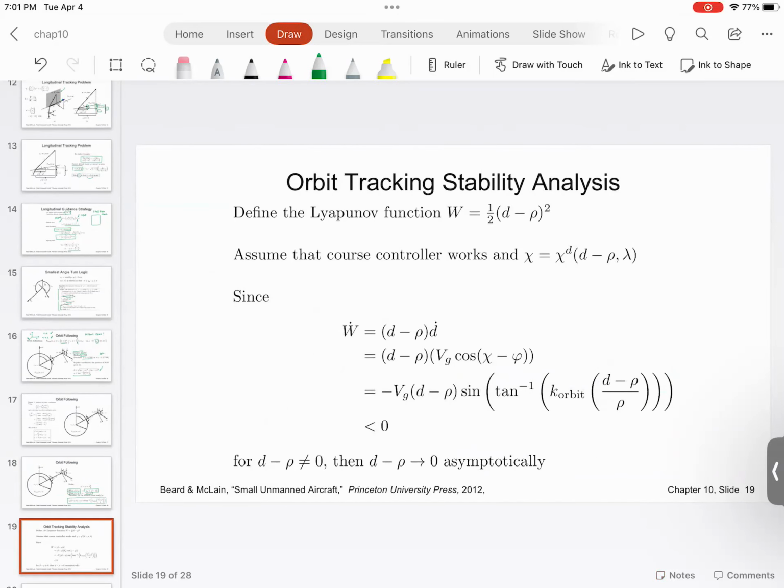Now, you can use the same Lyapunov type of technique to see if the orbit that this UAV is making is stable or unstable. What that means is you program the UAV to follow this circular path, and all of a sudden you have external wind. Because of that wind, the UAV is deviated from the path. Now, the next question is whether the UAV will come back to its original path, stay at the deviated path, or continue to deviate.